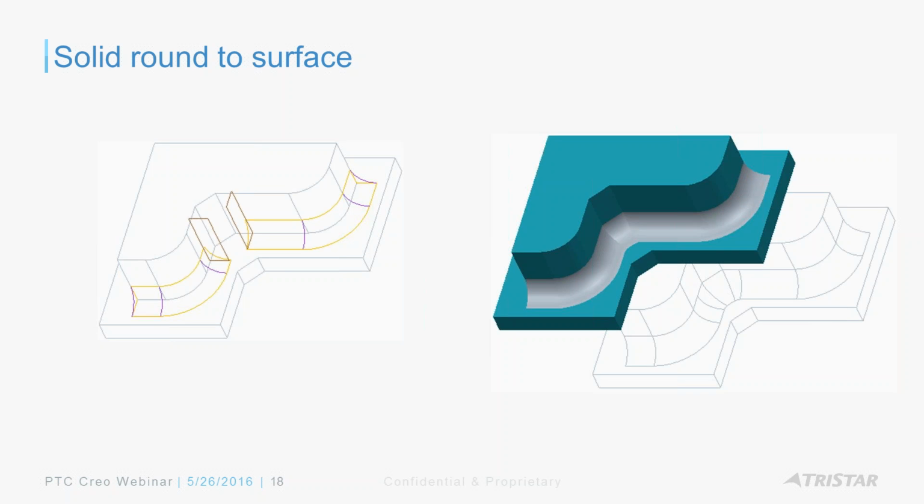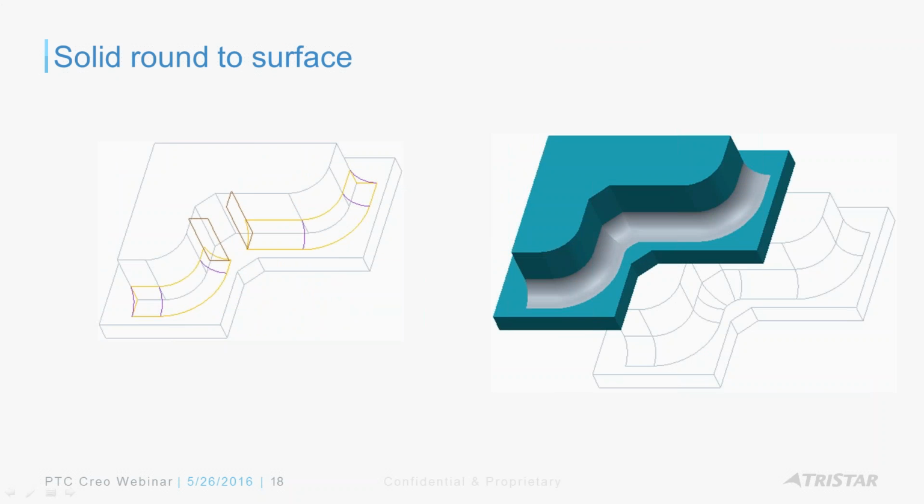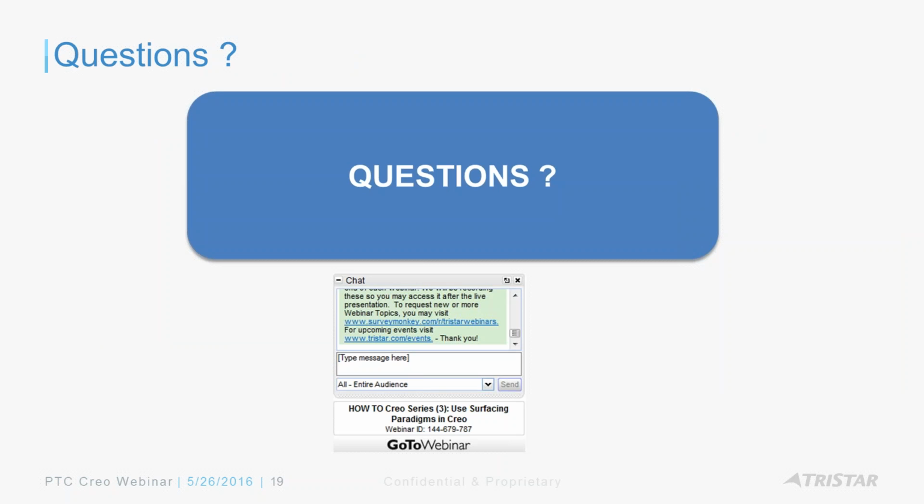So it's essentially not having material inside. In this case, you can see one-sided and two-sided edges of the surface there. These are all surfaces, and then I can work on this area where it's failing. I could add my own curves, for example, and do a boundary blend. So it's really like doing some patchwork, merging it, solidifying it. This is another common area where surface modeling is used heavily, wherein your model itself doesn't have a very organic or complex shape, but the solid modeling features fail in certain regions, and that's where you have to leverage the surfacing techniques.